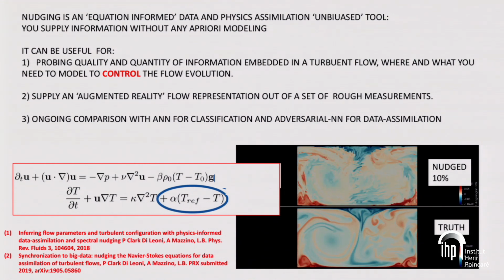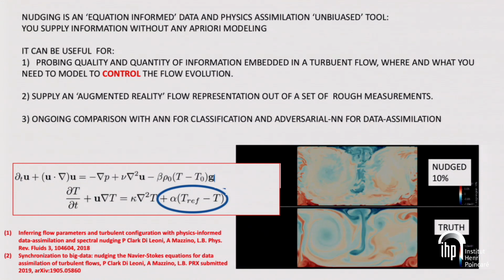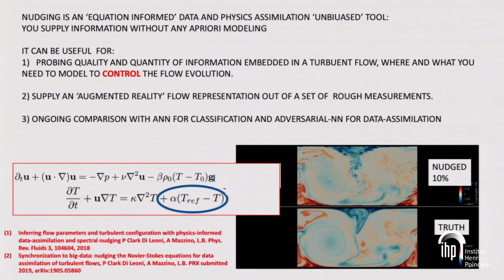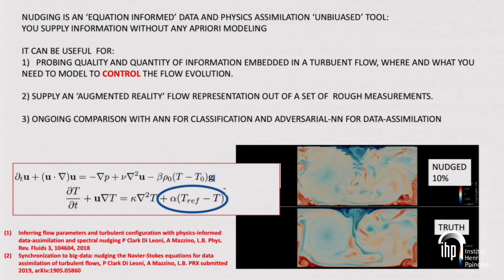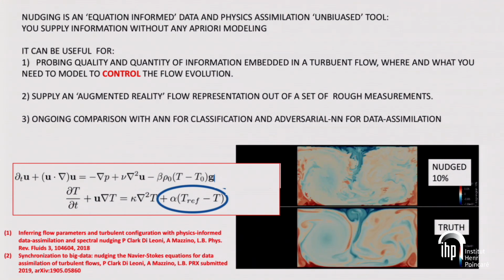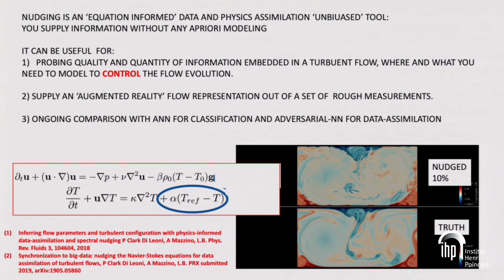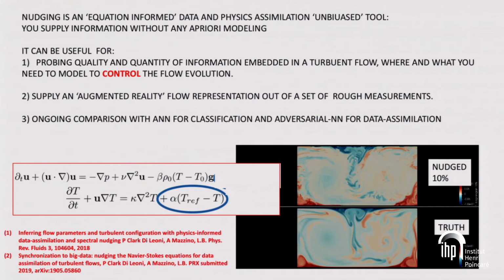Or maybe again, in Rayleigh-Bénard, it's easy to guess that if you have fixed anemometers and a fixed number of them, it will be better to put them at the boundaries than in the center. If you measure temperature in the center only, there is no way to guess what the running Rayleigh number is inside your cell, because inside the center the temperature profile is always flat, independently of the Rayleigh number.